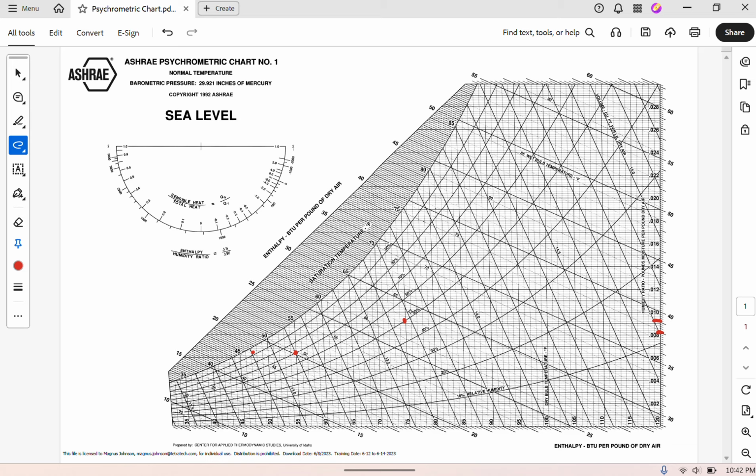So this means that from our point 1, we would have to go to point 2 before getting to point 3. So we would dehumidify or cool from point 1 to point 2, sensible and latent cooling, and then we would reheat our air up to point 3. And as you can imagine, this can be a more energy intensive process because you're putting in energy to cool and then heat. There are different strategies you can use in terms of conserving energy in such a situation, but the net result is that if you wanted to achieve this kind of latent cooling without going overkill with your sensible cooling, you would have to do some kind of a dehumidification and reheat type of situation.